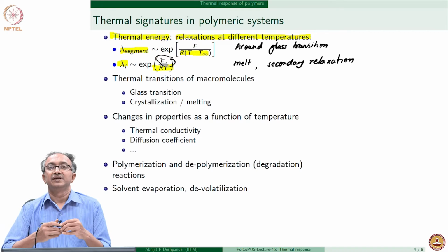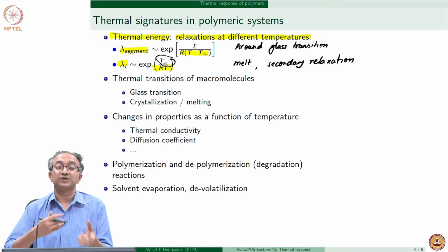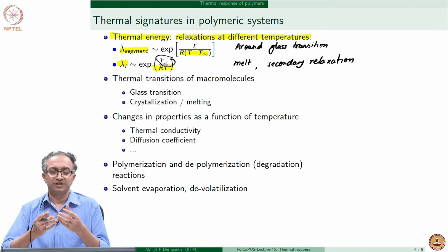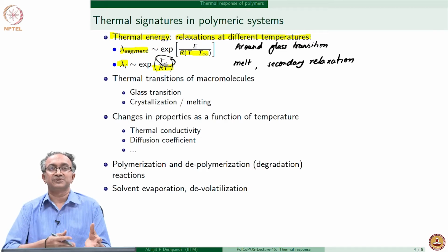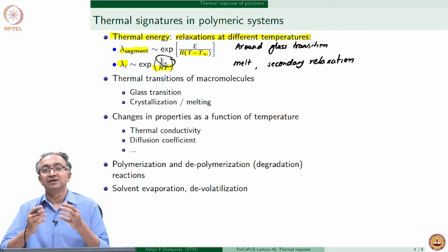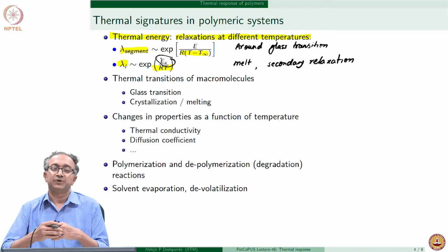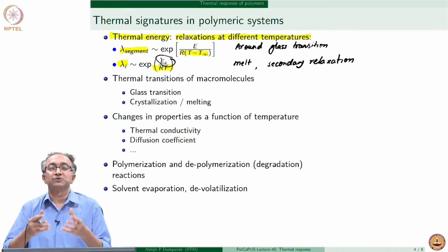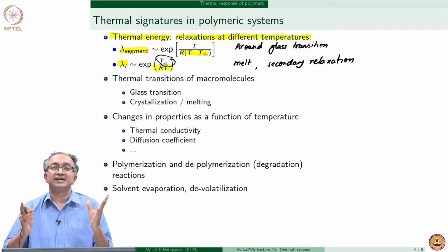If the rate of relaxation processes is very fast, or the relaxation time associated is very short, then again we get predominantly viscous type of response. So, in case of water, for example, water molecules going about, the time scales are picoseconds. And so, therefore, whether it is a millisecond phenomenon or a microsecond phenomenon or an hours phenomenon, water is a viscous fluid, because the time scales over which the relaxation processes are happening in the material are so fast compared to our time scales of interest. And so, all the relaxation processes happen, and therefore, water is a perfectly viscous dissipative material.